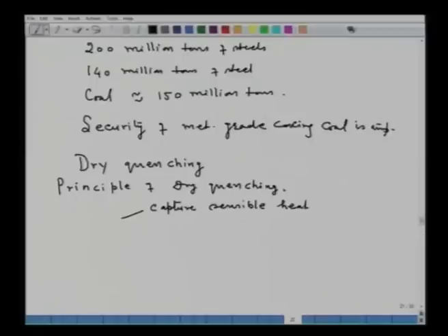That is, you have to design a reactor where coke and gas can be filled and heat exchange can occur. A counter current mechanism would be very useful, because it ensures a faster rate of heat transfer.